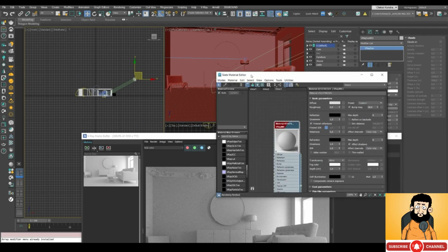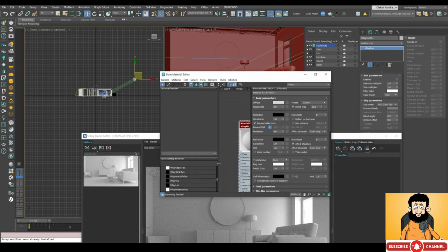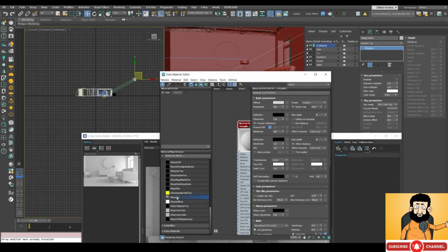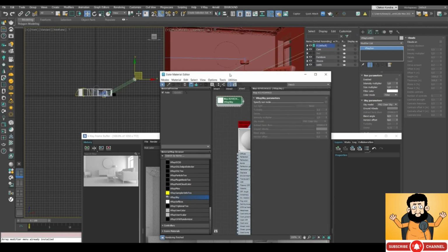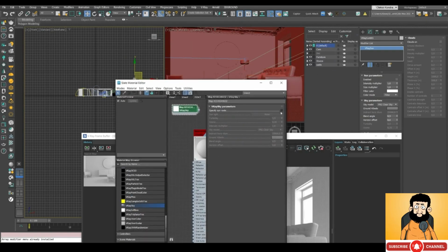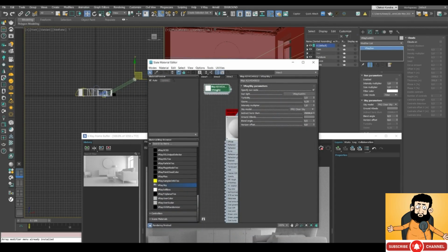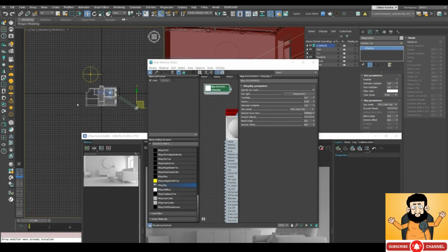So we open Material Editor window, select V-Ray Sky Map, and then simply drag V-Ray Sky to Material Editor. Then enable it by putting a check against Specify Sun node. And then goes the sunlight setting. So go ahead and click the Node button and then click our sun. Now we need to link V-Ray Sky to V-Ray Dome.